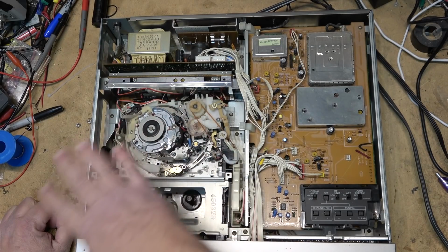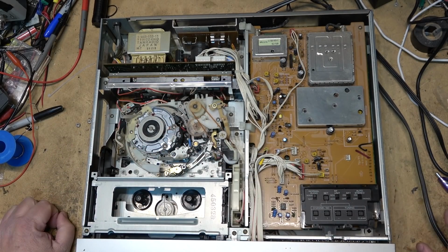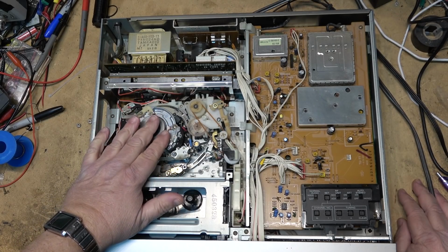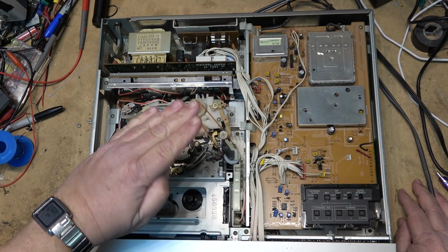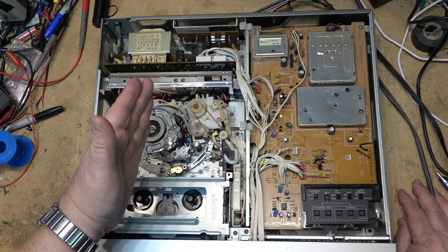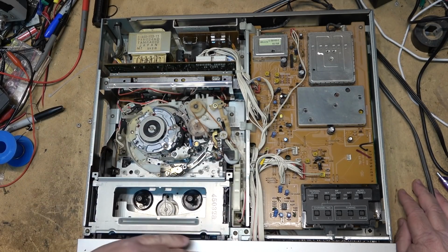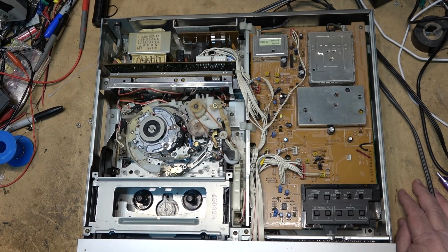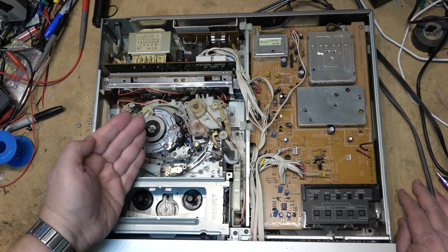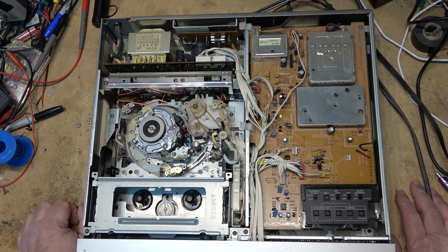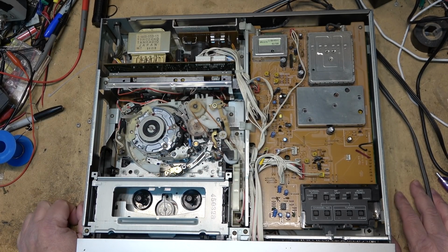So on Betamax they use azimuth recording, and the heads are plus and minus 7 degrees. One head is tilted 7 degrees negative of being perpendicular to the tape, and the other head is plus 7 degrees. Minus 7 degrees, plus 7 degrees. VHS was minus 6 on one and plus 6 on the other. The audio heads, though, were at like 30 degrees offset.